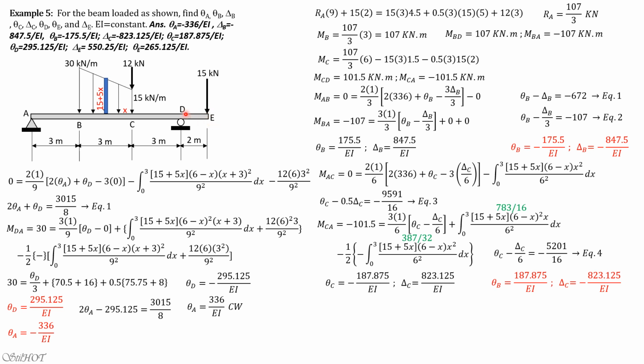So the formula would be 3EI over L, quantity theta D, here D minus P, then minus fixed end moment at D minus 1/2 fixed end moment at E. But because the loading between D and E is at the end, which is imagined fixed, there's no fixed end moment. By the way, we again assume that E is below, so that the rotation of the chord DE is clockwise. We have no issue with regards to the formula.